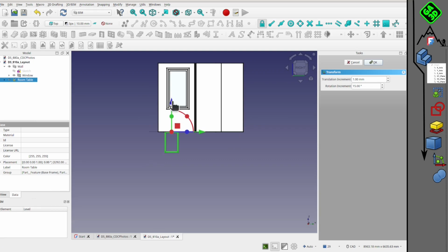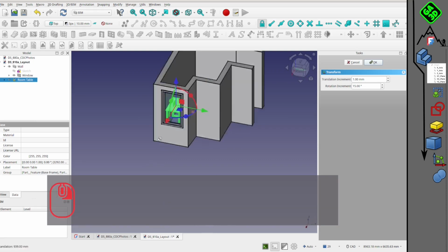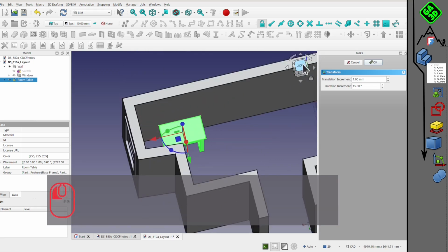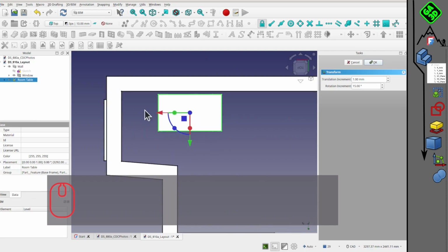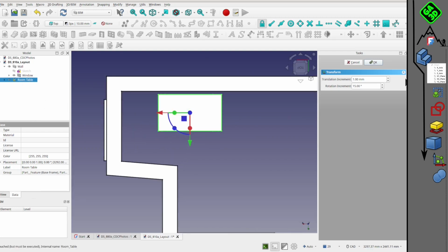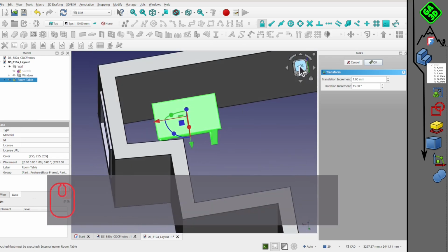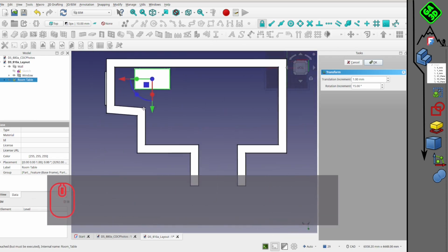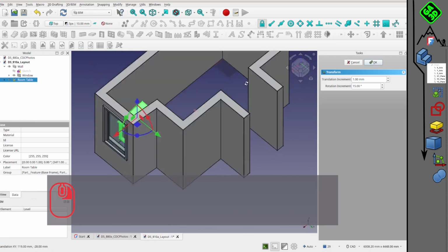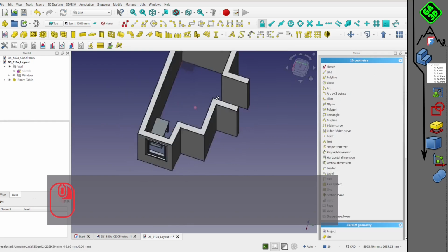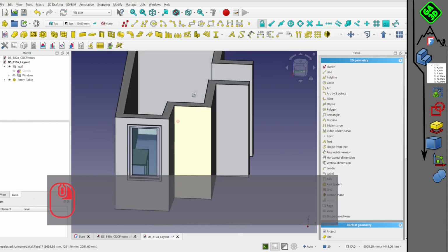Here, it was 2.5 meters. This allows us to render the volume of the room, the thickness of the wall. So here, by default, it's the brick wall, and 200 mm. The wall, in fact, is centered on the profile I drew, in fact, the interior space.